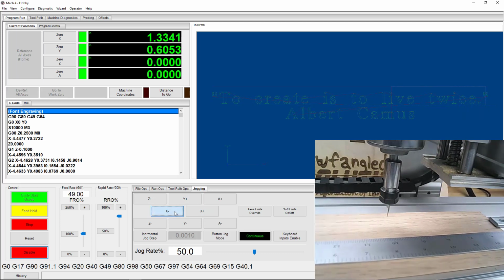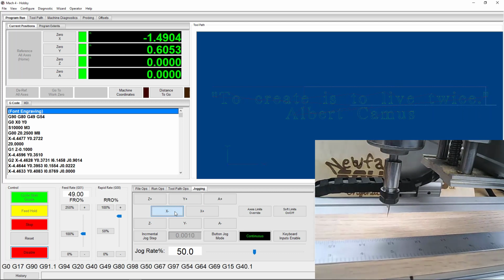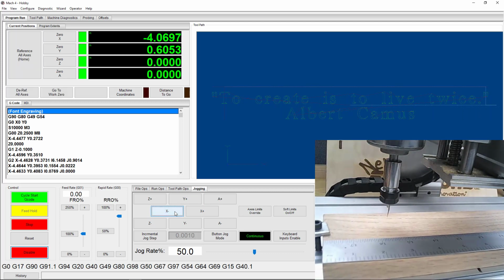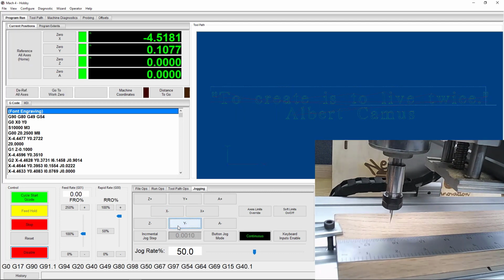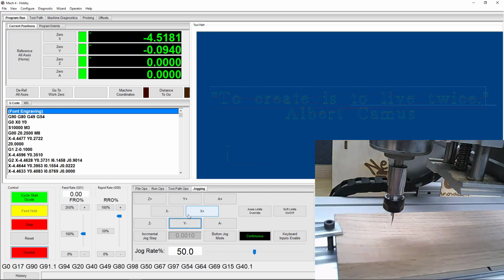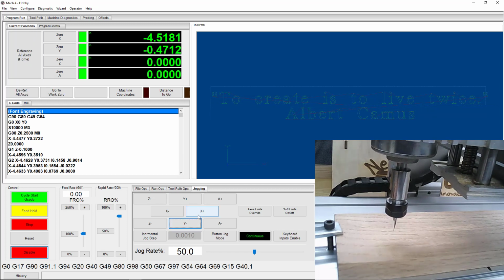Along with checking out the fit and sizing of your cut, you can also jog over your clamps and any other fixtures you might have to make sure they're not in the way. This is where you'll really familiarize yourself with the project, both in the virtual environment on your screen and in the physical one in front of you.